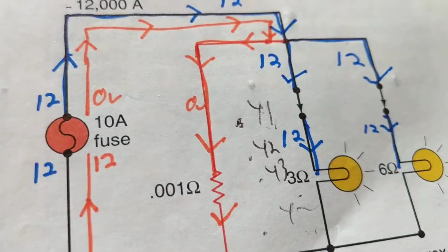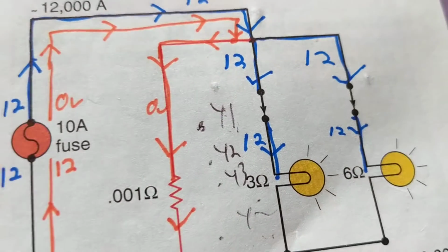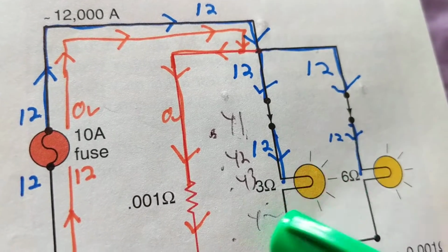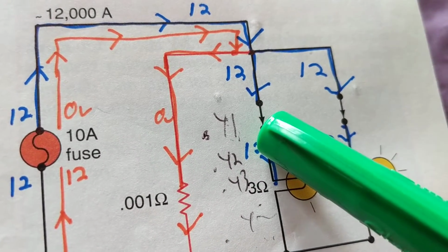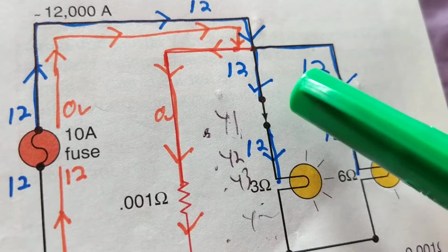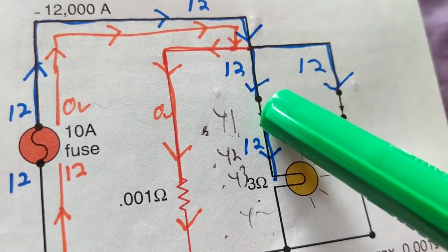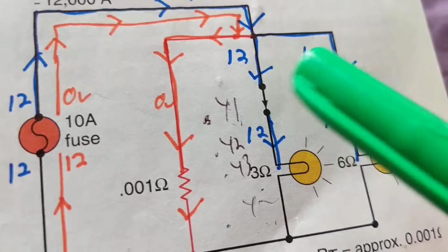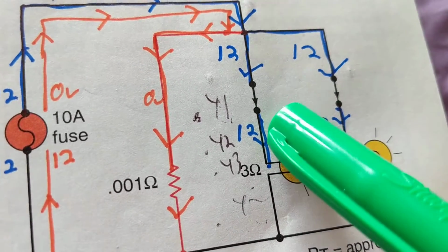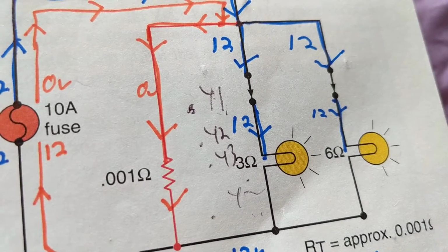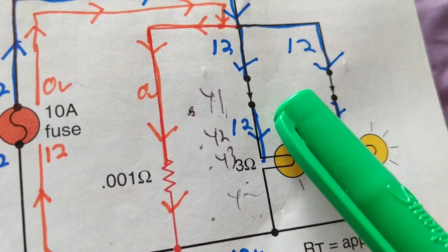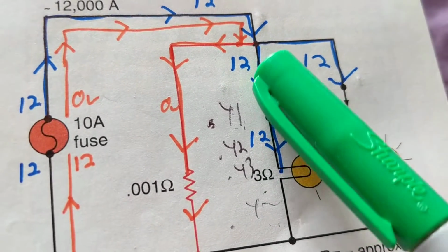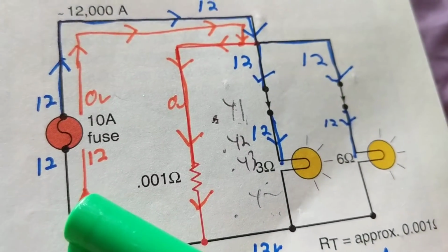An open. Again, we discussed this yesterday, an open. Where's an open? Guess what, where the open is? This is a connector. Let's say this is one wire of the connector. This is the other wire of the connector. Right here. See this switch over here? It's closed. See this switch over here? It's closed. We're going to open this one. How much are we going to measure over here with this open? If you said 12 volts with this open, you're wrong. We measure 0 volts. Why? Because we're not connected anymore to battery voltage through the fuse. We lost our connection.